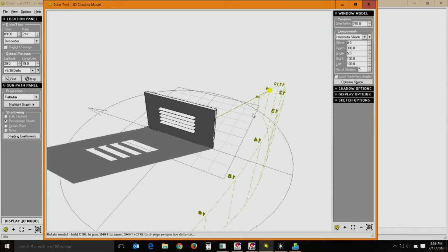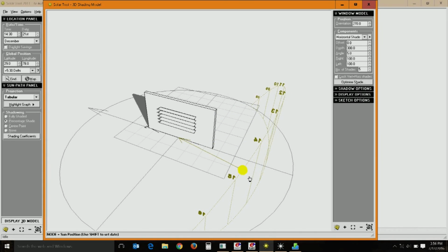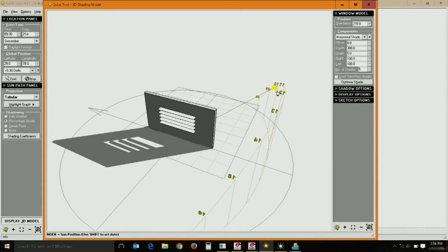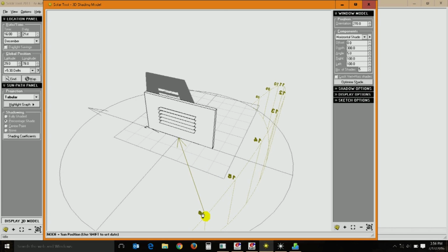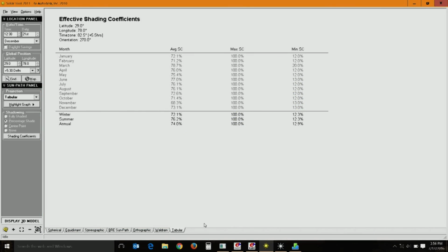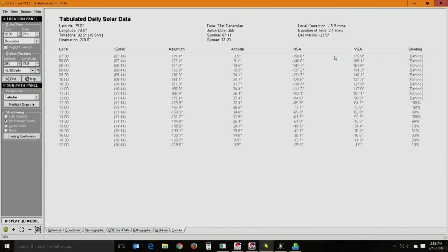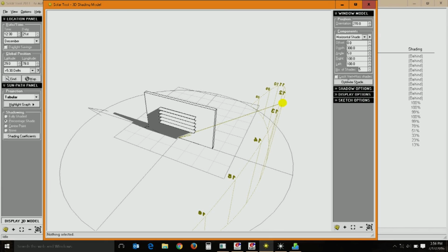If you reason it out clearly, the sun is towards the south. You have sun over the horizon, but you have direct incidence from the southern side. So, ideally you will need a vertical shading device as well. If you look at the horizontal and vertical shadow angles, you will get the answer. You will need a vertical shading device.